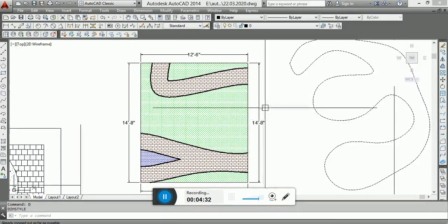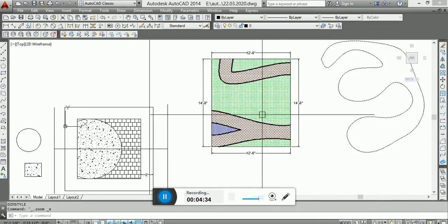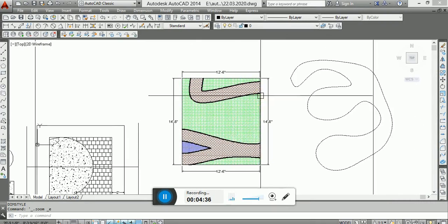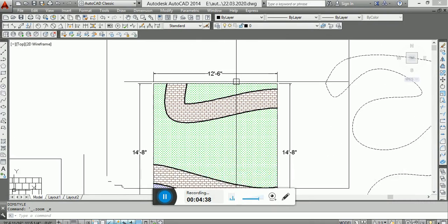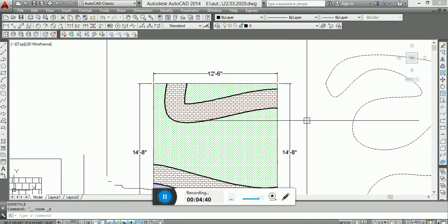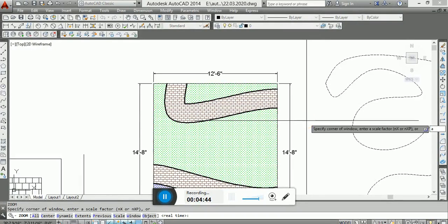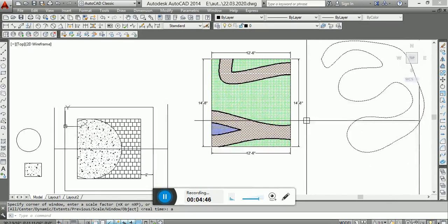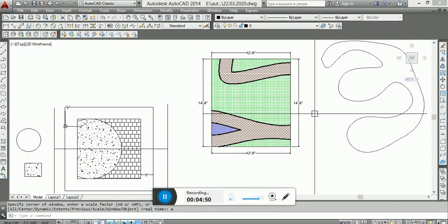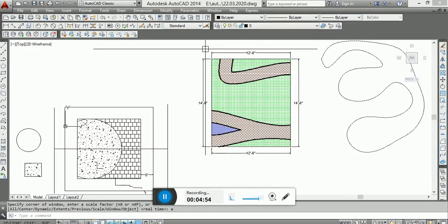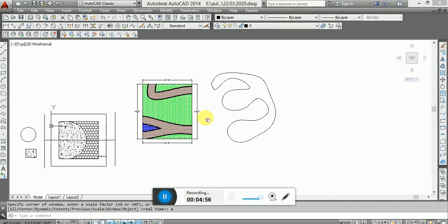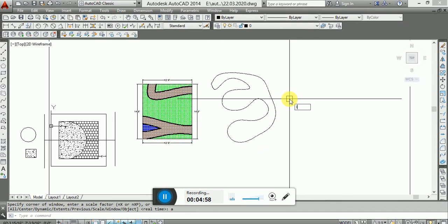And then if I go now very clearly, it happens sometimes in AutoCAD that you cannot zoom in and zoom out. So the command for zoom everything is Z space A space. Don't click in between anything. Then the whole window will be zoomed. Z space A space means zoom all. So this drawing is actually drawn like this.